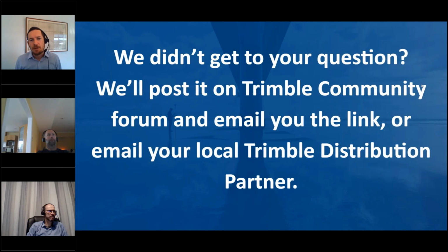Yeah, it might be a case of as-staked points. I tried converting, they won't convert. Okay, I've got a theory on this one, guys. We've seen a lot of issues in the past where if the geoid used on the controller is not a 100% match in Trimble Business Center, we can't do the conversion of as-staked points. So John, we might have to take this offline and try and work that out.